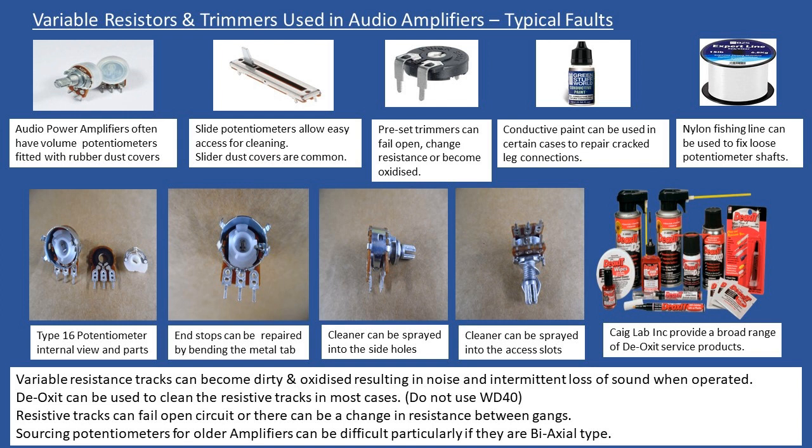Equally so, and this again is not uncommon, a customer may say, well, I've actually got a difference in volume, and it may not have anything to do with the processing circuit. You don't have some issue there when you put, for example, your oscilloscope onto there. The input signal for the left and right channel is the same amplitude going in, but then when it's coming out, and this is a dual pot, so it doesn't have two shafts, it's a single one, you get a difference.